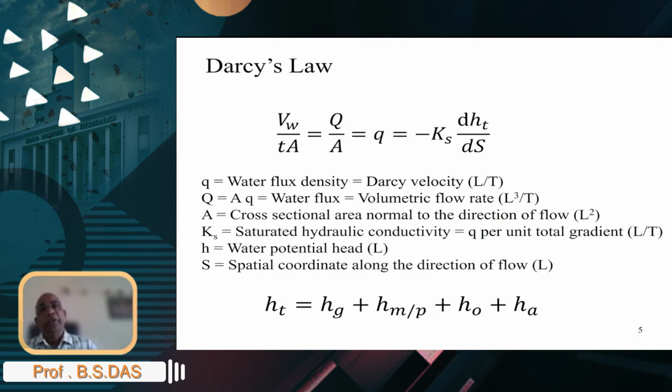Observe a couple of things here. We have now divided this big Q by the cross-sectional area, so that we are only looking at the intrinsic part of the flow process itself. Only the two intrinsic parts here. One is the conductivity, and one is the driving force, right? One, what really drives water, and the other, what opposes the flow of water. And so this Q over A, sometimes you can think of it as a kind of specific flux, and we call it a flux density. So you can see that it's the volume of water moving per unit area per unit time.